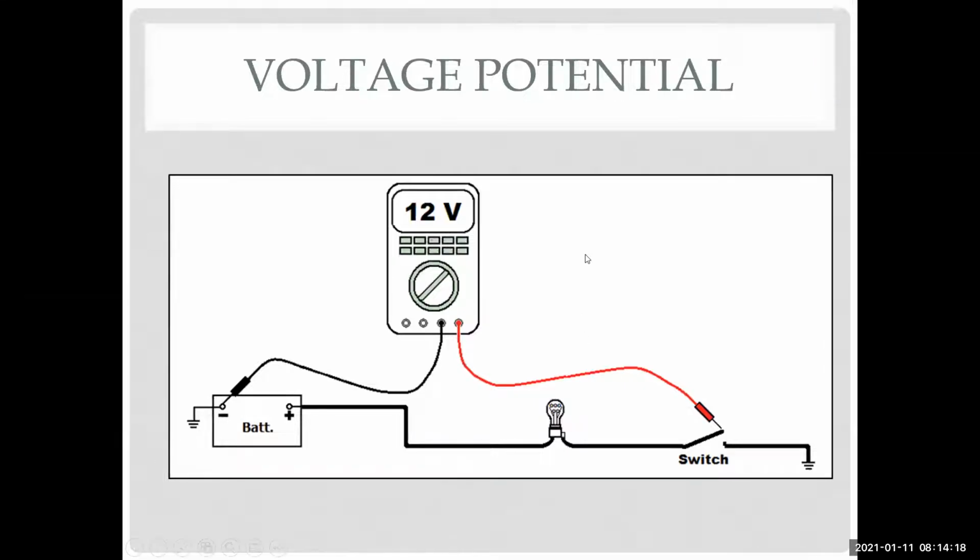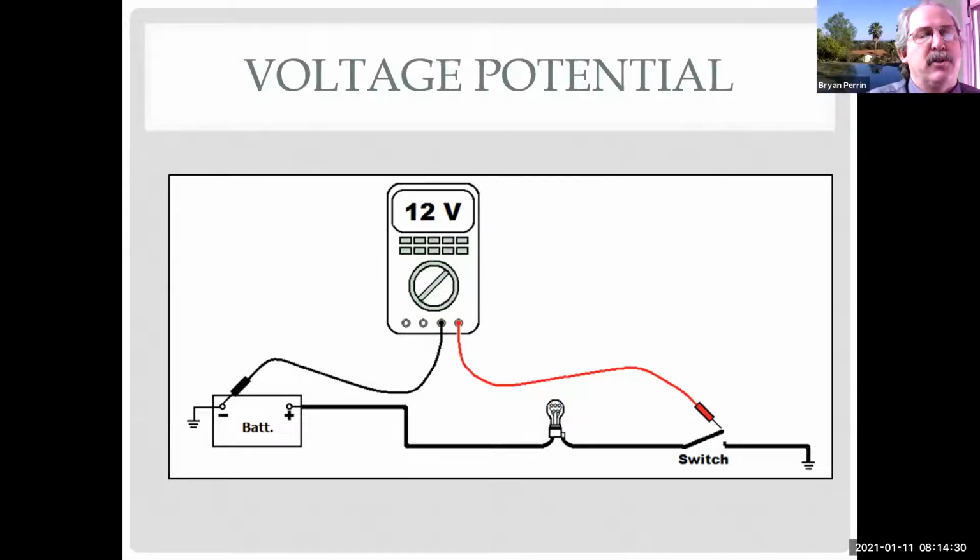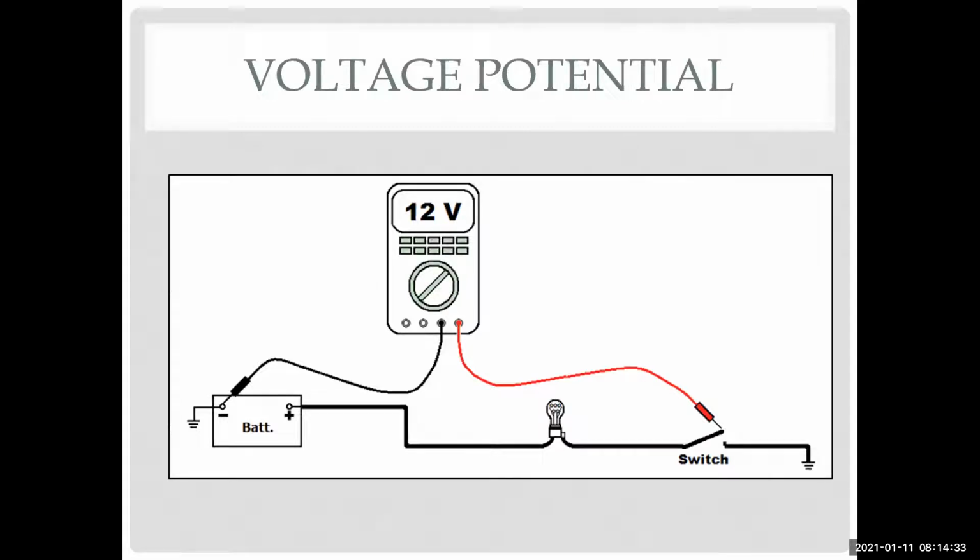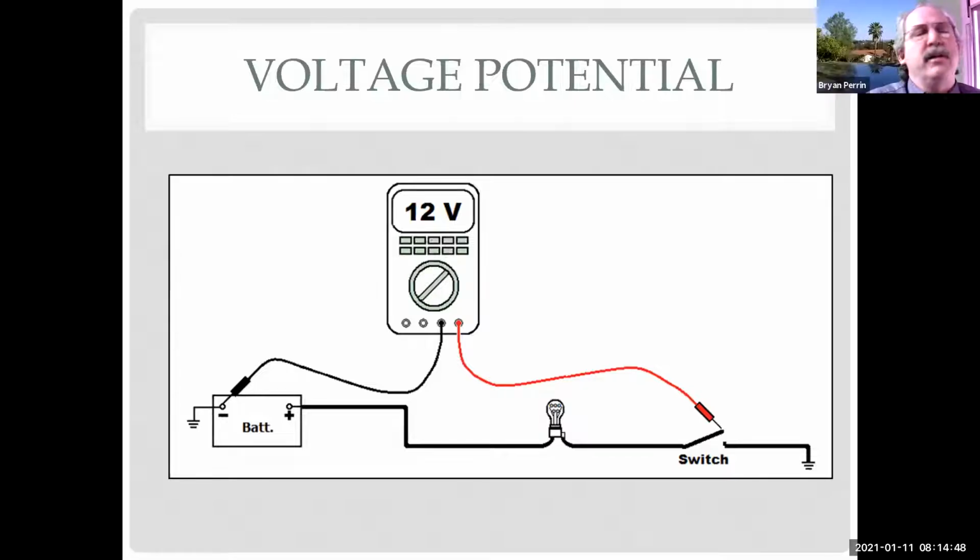Can I verify something so I'm understanding? If you close the switch, it becomes a conductor. Right. Well, if I close the switch, it becomes a complete circuit, right? So you wouldn't really be testing it at that point, only to see if there's any voltage drop with it closed, and then you'd start deciding, is it the switch or the back? Exactly. So here I know I should have 12 volts with the switch open. If I close the switch and I still have 12 volts, either I have a bad switch contact or maybe the ground's not connected.